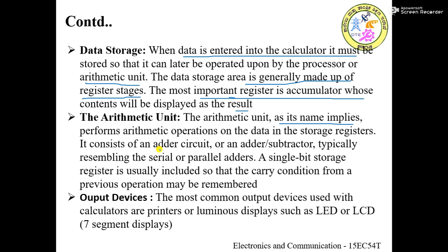And here it consists of an adder circuit, as I already told you. If you want to perform subtraction, it is also carried out using the adder circuit only, in the two's complement manner. And if you want to do a multiplication, it can be carried out with the successive addition method. And if you want to carry out the division operation, it is done with the successive subtraction method. So all these are carried out using the adder circuit, a single adder circuit only.